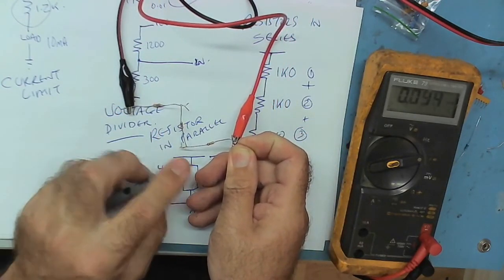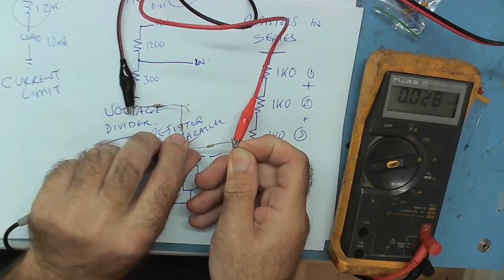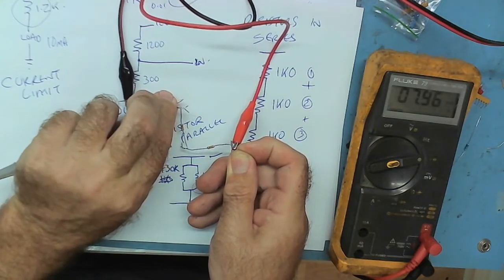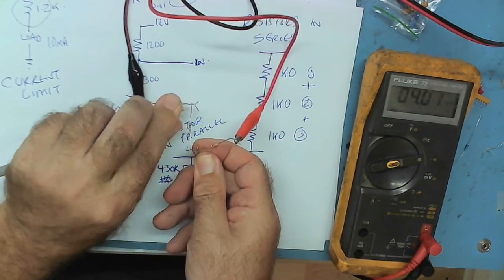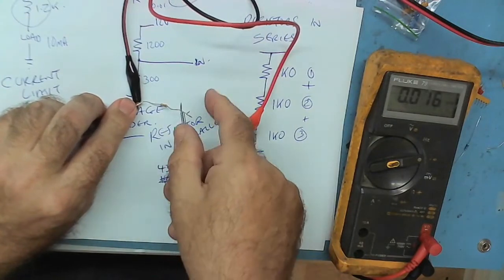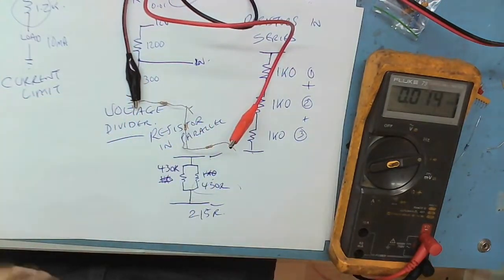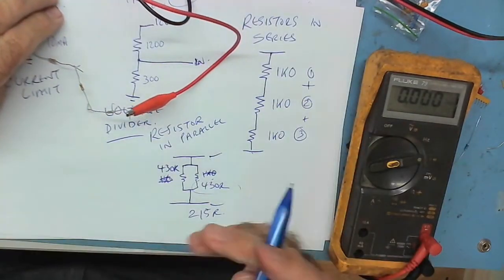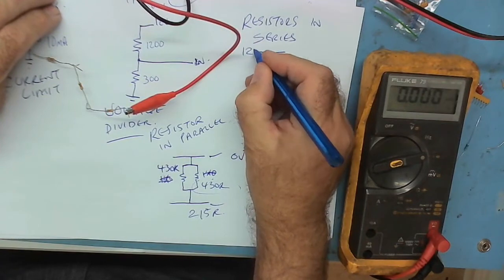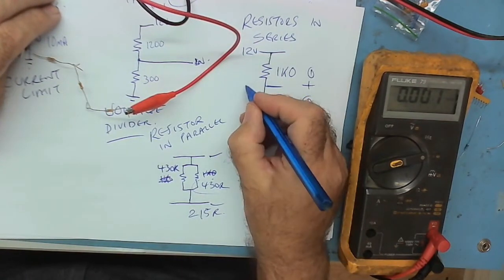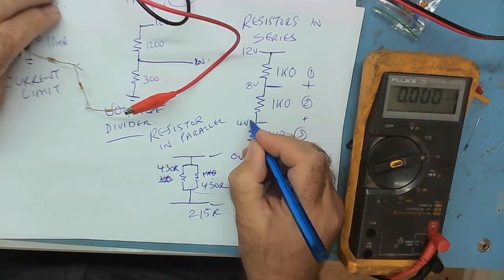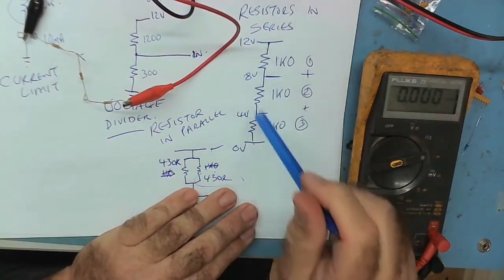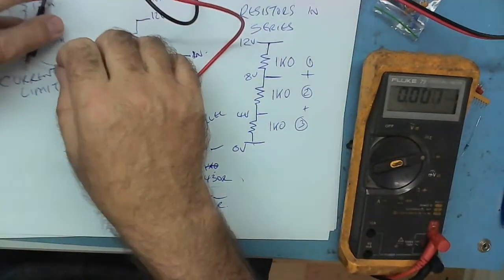So what do you think will be across the first one, there's 3 of them? It's a 1 kilo ohms. 4, yeah? What do you think is down to the next one? 8. So across each of these is 4, because the resistors are all the same value. 4, 4, 4. That's like I drew here, yeah? So if you've got 0 volts here and 12 volts here, here you will have 8 volts, and here you will have 4 volts. It's like a ladder, yeah? And these are all the same value. The amount of current flowing will depend on the value of those resistances.